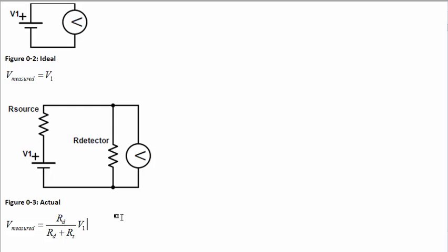Sources in a lab will usually tell you how much their output impedance is, so that you can do things like match the input impedance so that you get exactly the voltage that it's listing when you do maximum power transfer. This can be kind of confusing to new lab students.